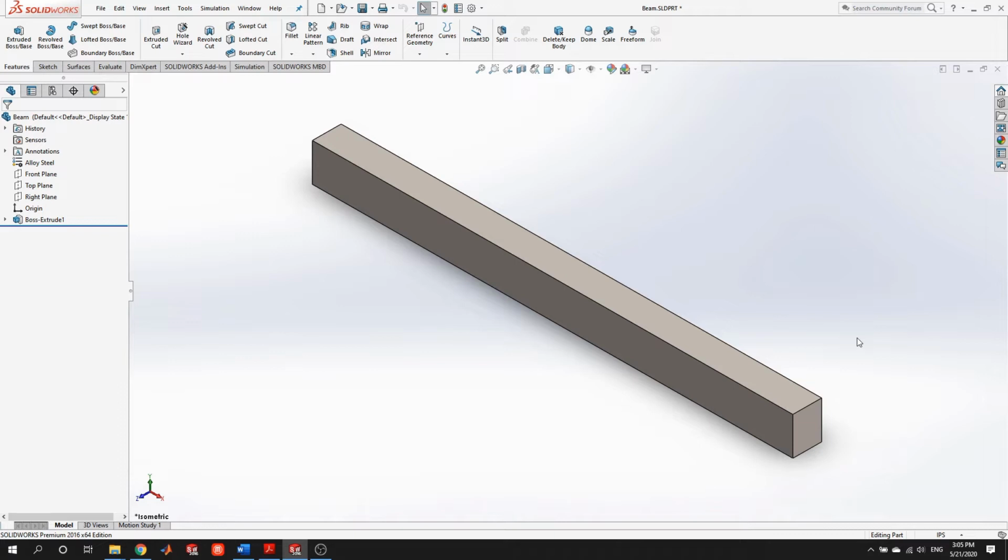So a lot of times you want to clean up the model. This can mean maybe if we had a small little extrusion here that's really not contributing to the strength of the beam, that we don't suspect to really compromise the strength of the part by it being removed. This will help it mesh better and obviously get more consistent results. So geometry cleanup is kind of the last step in geometry creation.